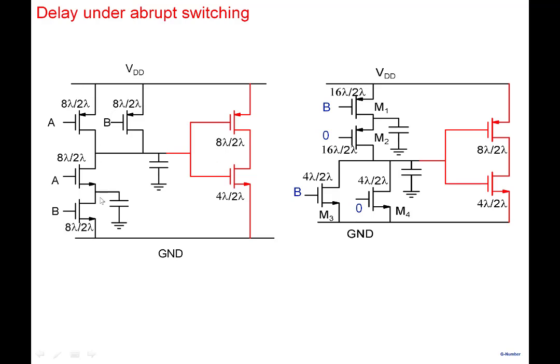So this is our NAND gate, whose load is an inverter. And this is a NOR gate, whose load is again an inverter. Let's compare the two. For the NAND gate, we had calculated earlier the overall output capacitance, taking into account all the capacitances from the NAND gate itself and the inverter, lumping them all up here, and it was about 21 femtofarad.